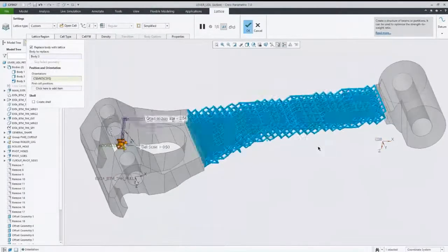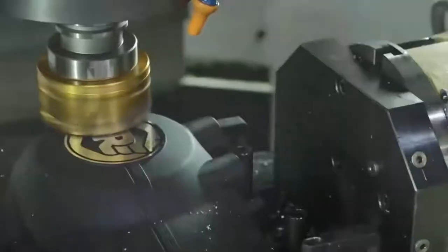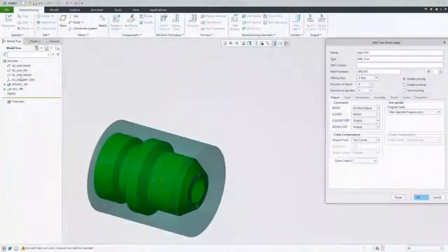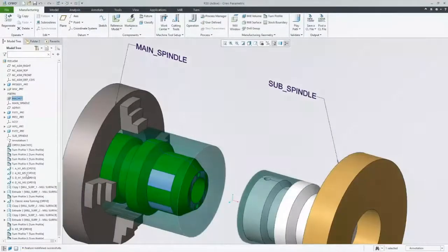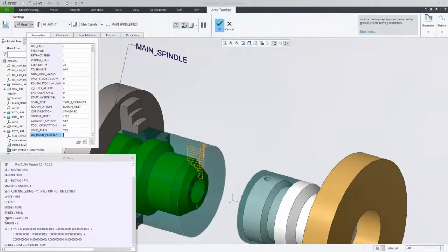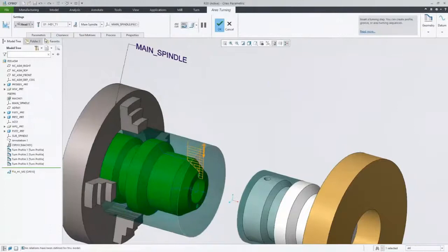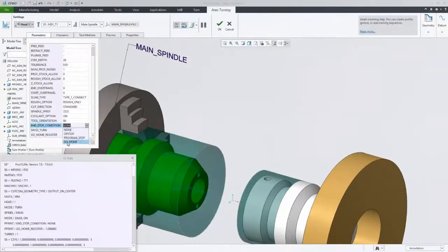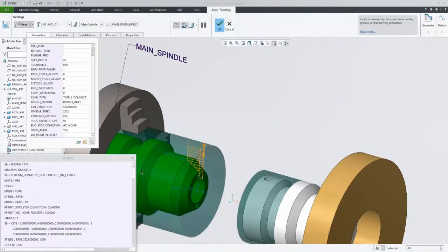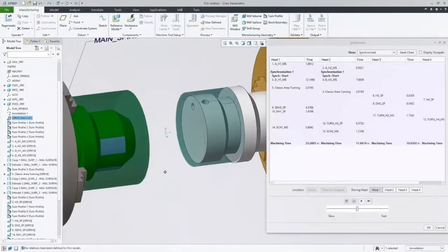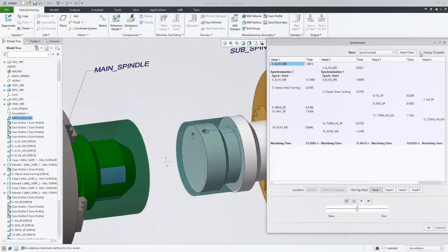Creo 7.0 also features significant enhancements for traditional or subtractive computer-aided manufacturing processes, starting with support for Swiss-type turning machines in Creo's NC suite. This is especially useful for a broad range of high-throughput production operations. Creo 7.0 also features several productivity and UI improvements, including support for multiple go-home positions for advanced machine types, eliminating the need for lengthy custom commands, and synchronized toolpath highlighting, making it easier to visualize sequences in a clear and simple way while you work.